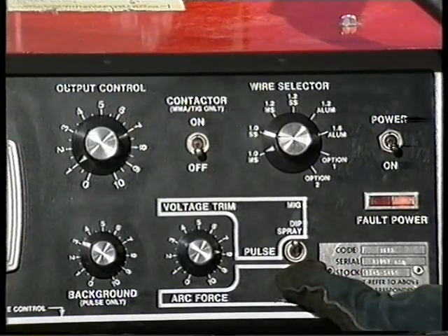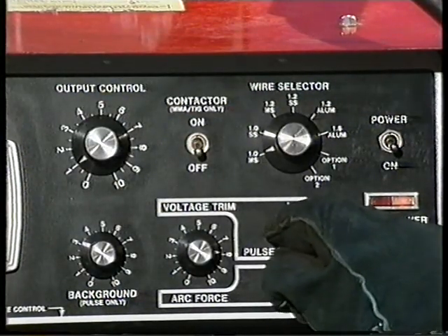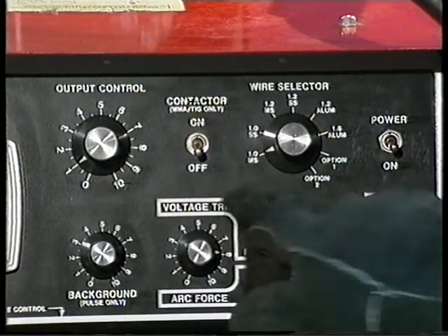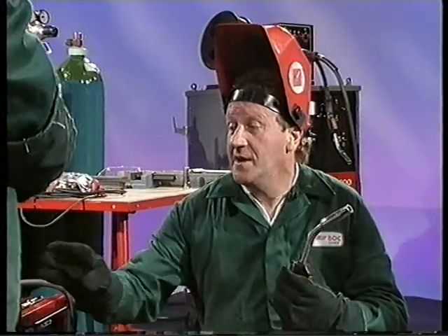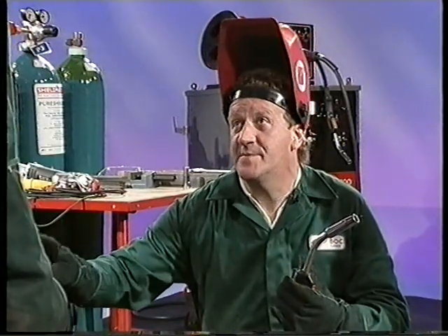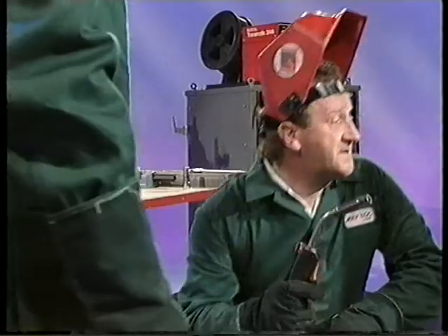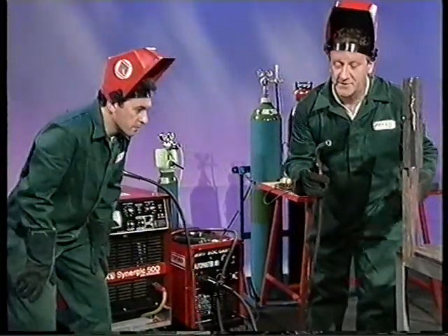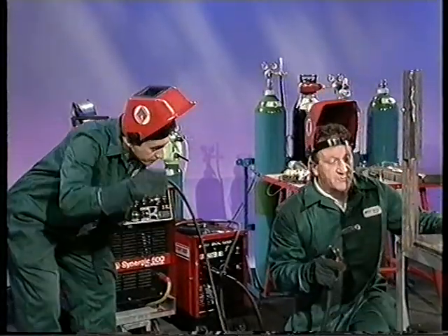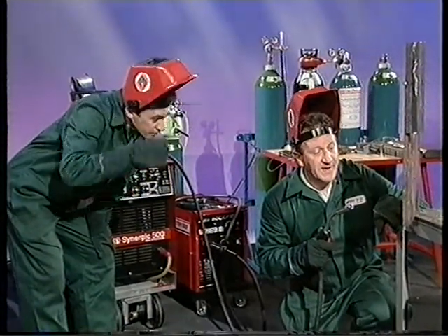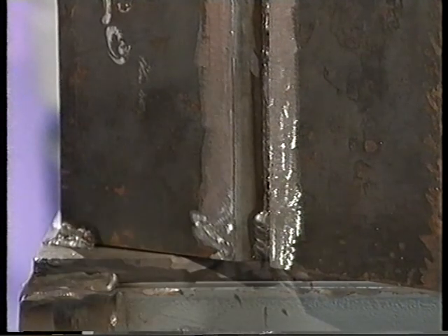We're already at the moment in dip, so we go over into pulse. The program's already selected for 1mm mild steel wire, and from that previous little weld that I did, I know that these conditions are more or less set the same for pulse as they were for the dip. Right. So we'll come over and just snip the end of the wire, and we'll be building up on this weld here. Again, I'll probably start back on the previous run, which will leave a little lump that we'll grind off afterwards.